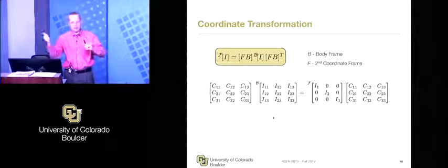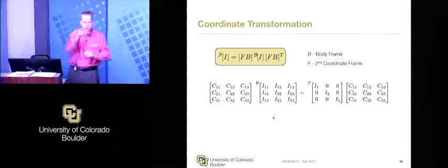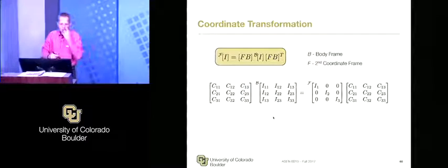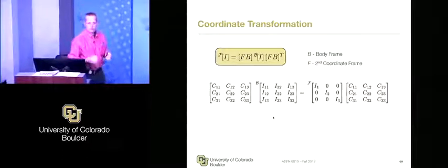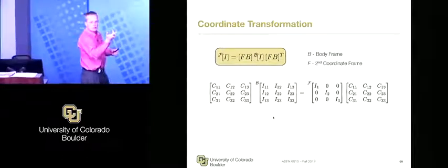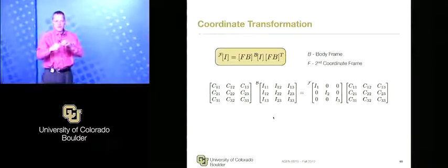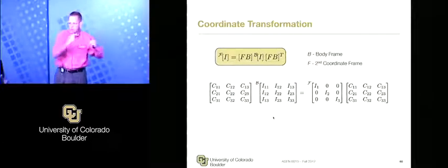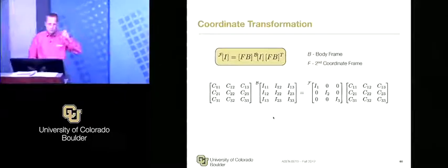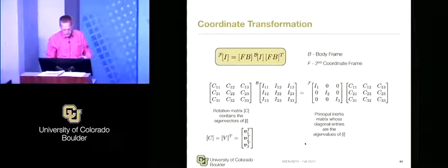It might give you plus that axis or minus the axis. So when you construct this yourself, you can't just have MATLAB do it all for you. You have to make sure you end up with a right-handed coordinate system. So F1 crossed F2 gives you F3. And if you rearrange how you're putting F1 and F2 in there, then of course the inertias have to be rearranged accordingly. All right? So just some subtle things there, but that's basically the relationship.